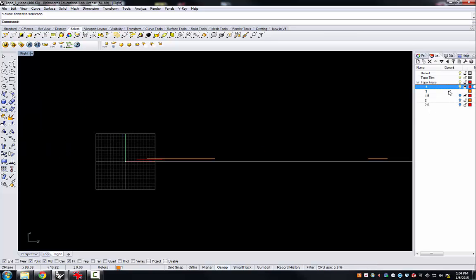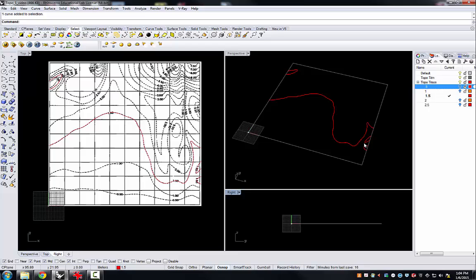And you can go through sequentially, moving all of this geometry up to the correct layer. You don't really need to zoom in and out quite as much as I've been doing. You could select it with a window to get all of that geometry, and type move. We're now working in the 1.5 meter level, so click on that endpoint, type in 1.5 meters, hit return, hold shift so that it's going straight up, and move that geometry up.